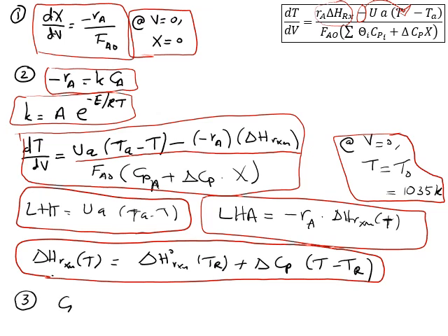That is writing an equation for Ca. Ca equals Fa over v, and Fa as a function of x equals Fa naught times (1 minus x). Divided by epsilon. Is epsilon constant or variable? First I have to ask, which phase is the reaction in?